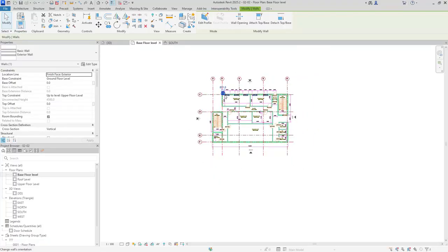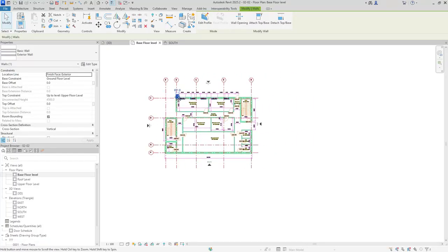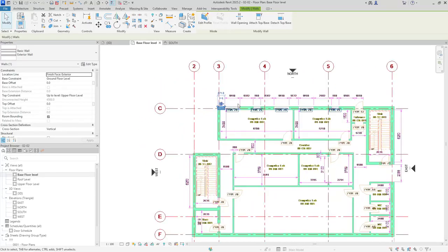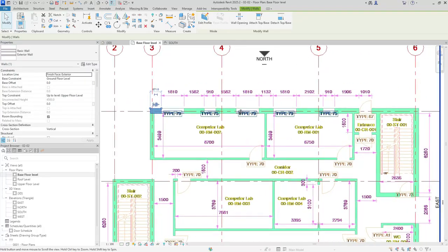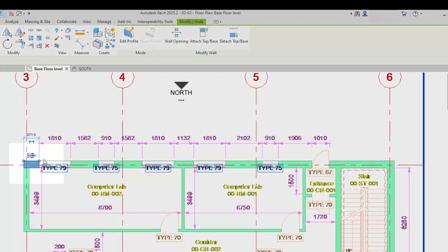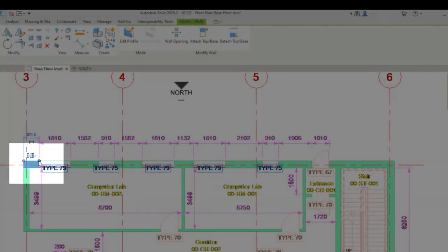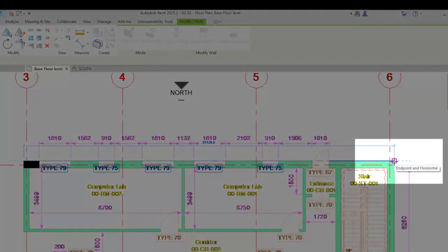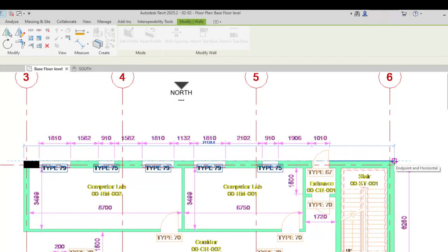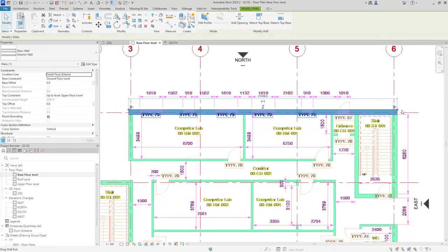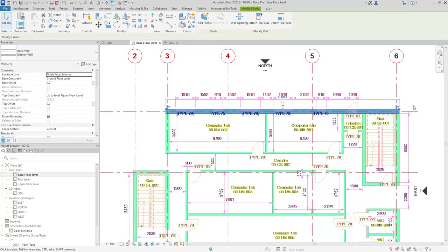Using the wheel on your mouse, roll the wheel backwards to zoom out from the view. Clicking and holding the wheel while moving the mouse pans the view. You can pan left or right. You can use both of these to good effect so that you can see the entire wall length in one view. When you do, place your cursor on the small grip and drag it to edit the length of the wall. When your cursor is over the end corner, you'll notice a small magenta square symbol indicating the endpoint snap. Let go of the grip at this point to snap the wall length to the end of the 2D line.